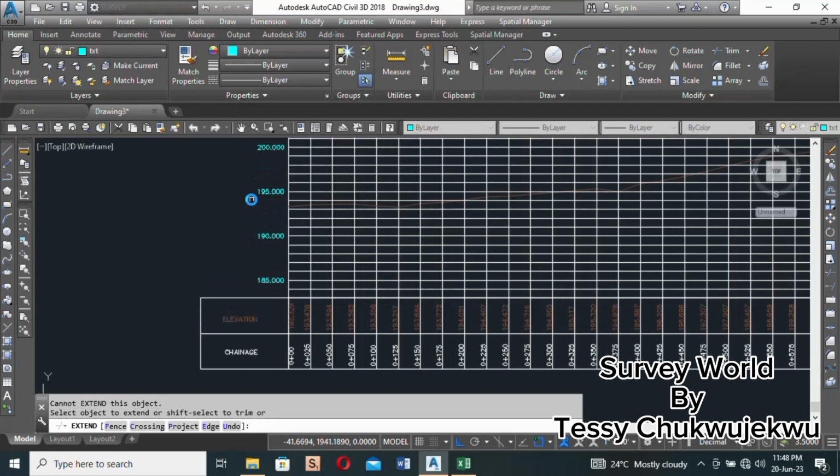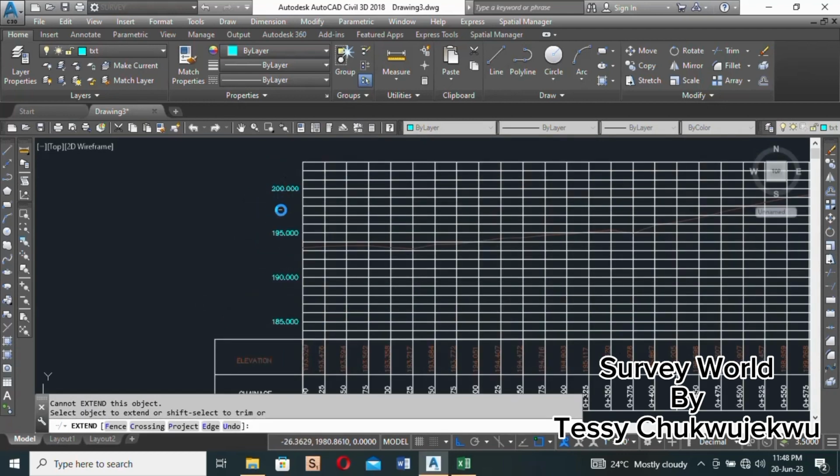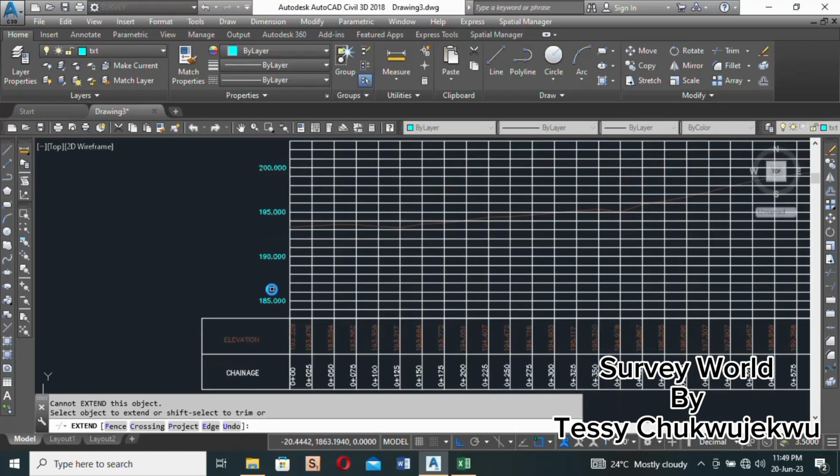Now, having done this, the next step is to mark our elevation, that's on our vertical axis. Now we can use what we have here, but the problem with this is you cannot tell where the marking, where these elevation marks are, the columns they are for, the lines they are for. So that's where elevation marker comes in. Remember I told you we'll be using two applications for this, the profile 100 and the elevation marker. So now I will load elevation marker right now.